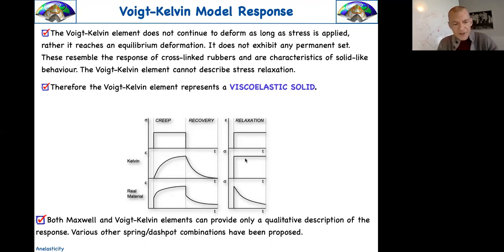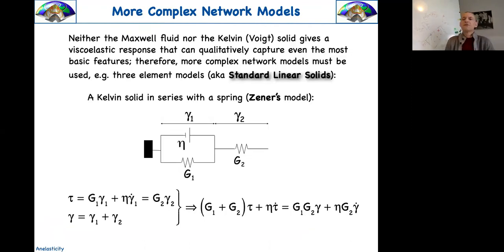Okay, what is the simplest rheological model that is going near to what we want? Well, it's called the standard linear solid, and there are many implementations of it. We will take the simplest one, which is this one. It's called the Zener model. Now, again, in the next slides, you will see many formulas appear. Just use the logic. Okay, let's take this example. Now we have a Kelvin on the left, now in series with a spring. This kind of implementation is called the Zener one.